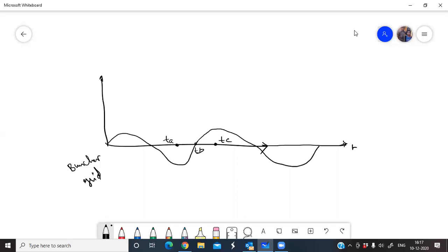You can take T1, T2, T3 also, no problem, nothing wrong in that. So here what I want to say is the electrons are formed like bunches after traveling some distance. So I want to assume the distance as the bunching distance, and I want to denote that with delta L. After traveling some distance, some bunching occurs. So already I told that when Vs equal to 0, that is traveling with uniform velocity.